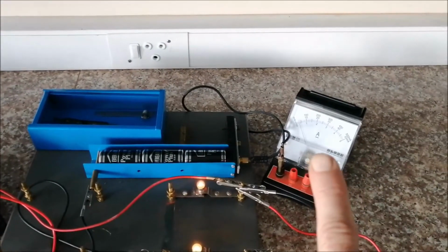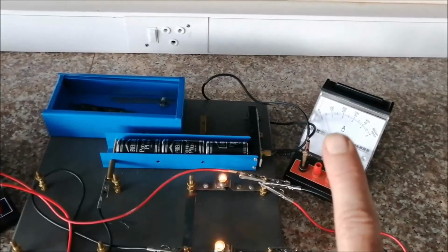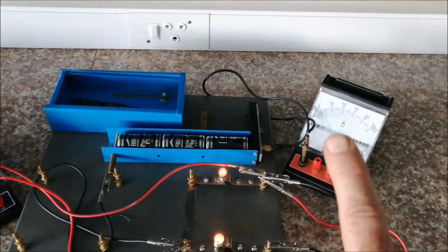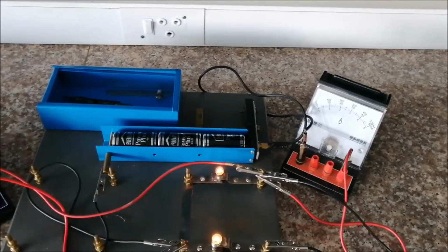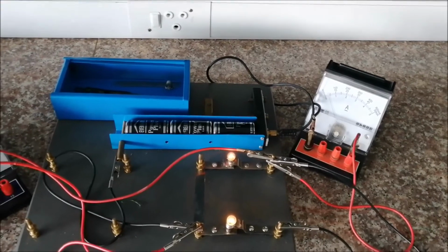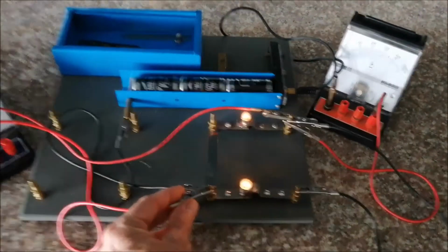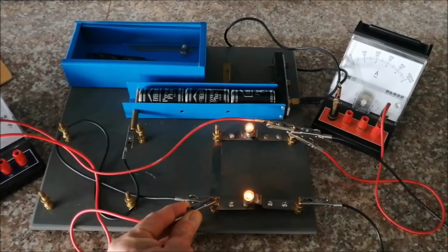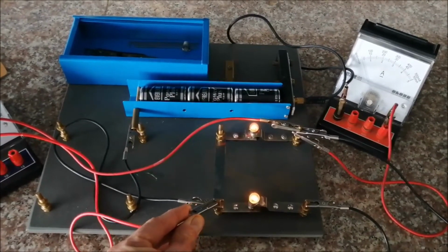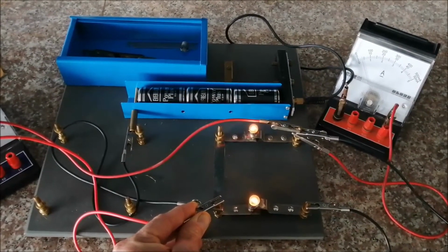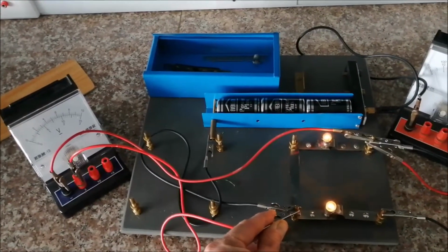Then an ammeter, we must connect it in series with the circuit. Now an ammeter has very, very low resistance. We talk about it having negligible resistance, and that measures the amount of current that is flowing through the circuit. And you can see here, let's just show you, this is the voltmeter lead, and you can see that if I disconnect and reconnect the voltmeter lead, it does not affect the current flowing in the circuit, because there is no current flowing through the leads that lead to the voltmeter.